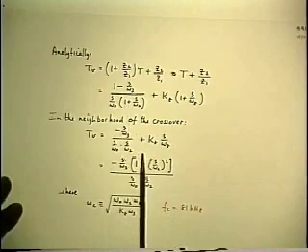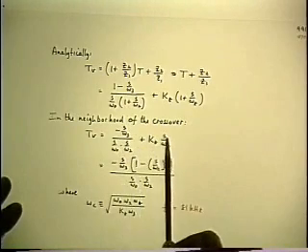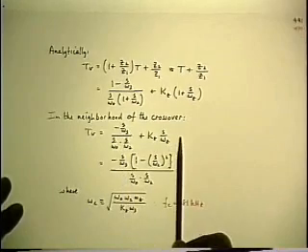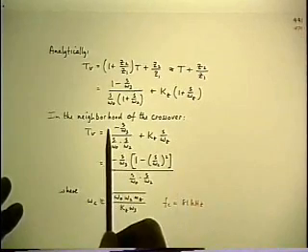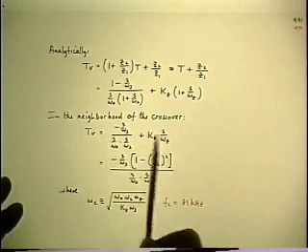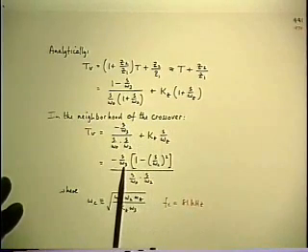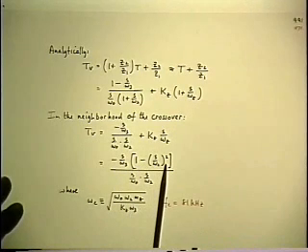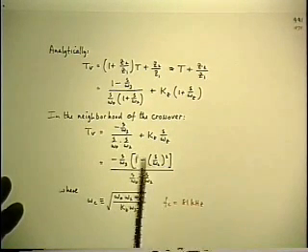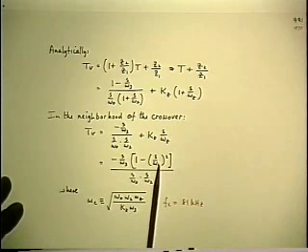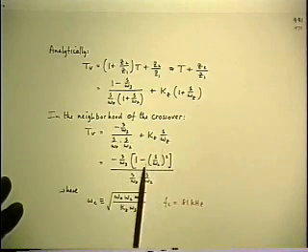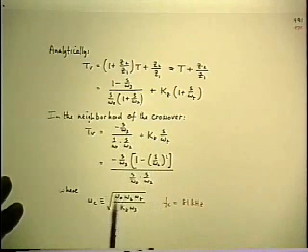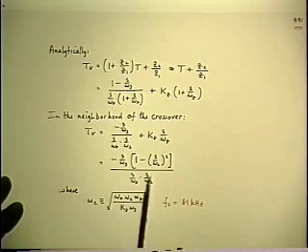So when I do that, now I cross multiply and I collect powers of S, and I still get a cubic equation, but there's no constant term. So I can factor an S out of the whole thing. And what's left behind is a quadratic. And I know what that corner frequency omega c is, because I get it when I factor the S out. When I factor it out, omega c is equal to this stuff. So I know what it is analytically.